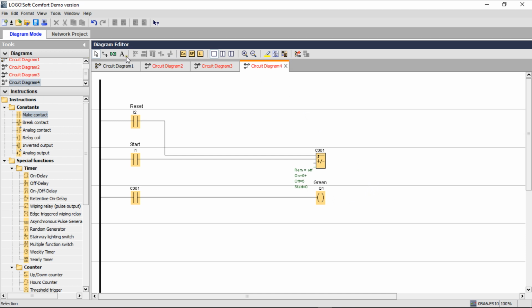All right, so for that we will need to be able to count up and to count down. Remember, in the previous video or in our notes, we discussed that for this PLC's up-down counter, when the direction is powered, it will count down.